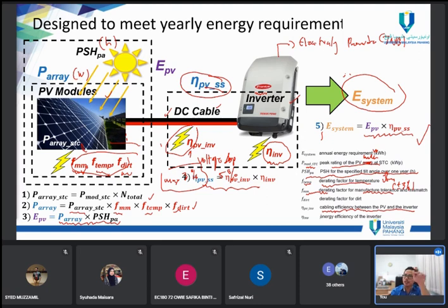Okay, Muzamil, we do not include storage batteries in the grid connected system. You are not allowed to put batteries in the grid connected system. But for the self-consumption based PV system, that is different. That is a different structure, which originally also comes from the standalone. When we talk about batteries, that only applies to the standalone PV, not the grid connected. Okay, Muzamil?